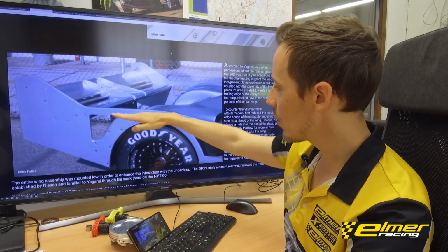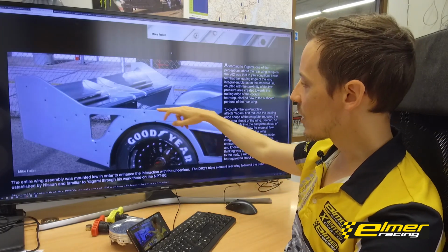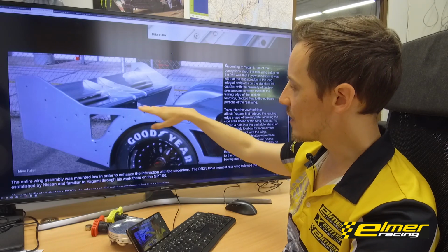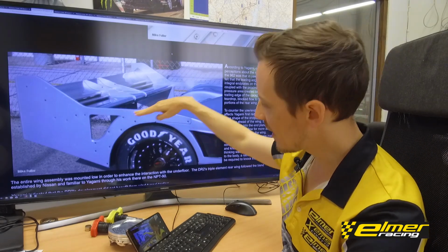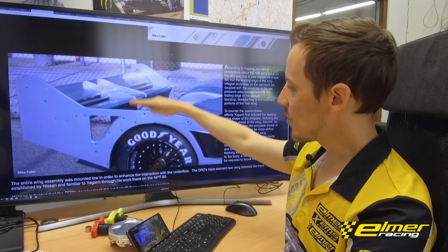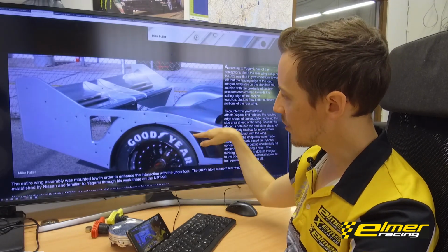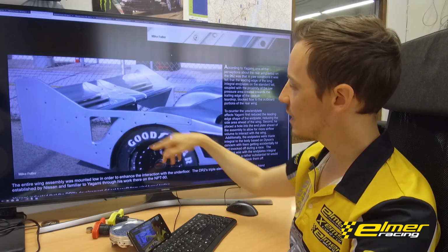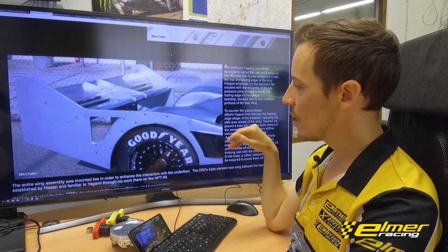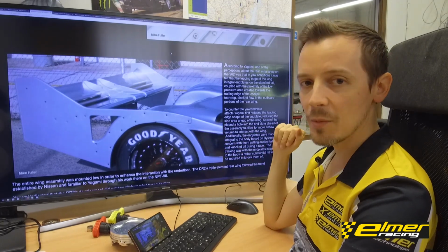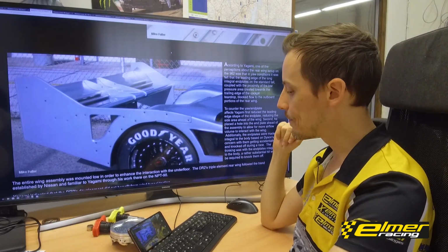Well, it's not super low either, but the rear wheel arches here are reasonably in line with the wing. So you have the wing and can create a high flow velocity underneath that wing, and by placing it correctly with the airflow, you can use that velocity increase to get a higher suction from underneath your car, and that is what will really help produce lots of downforce.